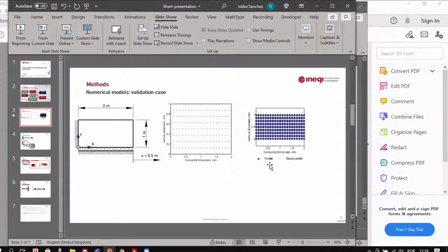Anyway, we implemented the Ogden model into another meshless method, the NNRPIM. It is similar to the one I presented before. The only difference is that this one doesn't require a background mesh. This one only requires the nodes, and from that we create everything, which is more meshless than the other. But this is a little variation. The equations are the same.